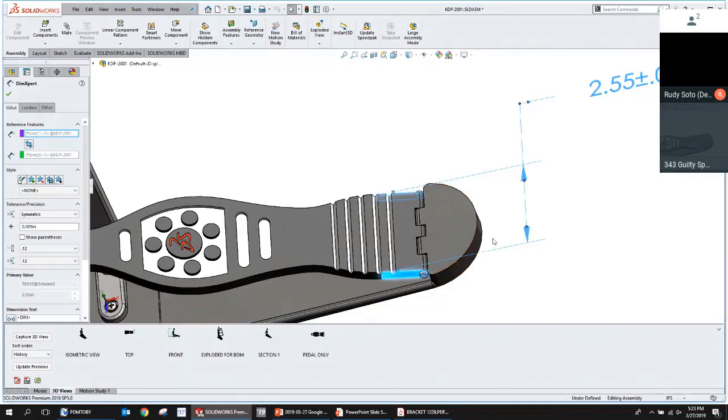So the information that's captured in that model, the model dimension, tolerances, how is that useful? Where does that actually land? In your drawing, if you do model, import model, then dimension model, you can have import annotations. So you can use it there, yep, or you can use it in some of the downstream applications like the inspection process or the machining process. That's where it's the most useful. And so you don't have to put it on an annotation view to import it.